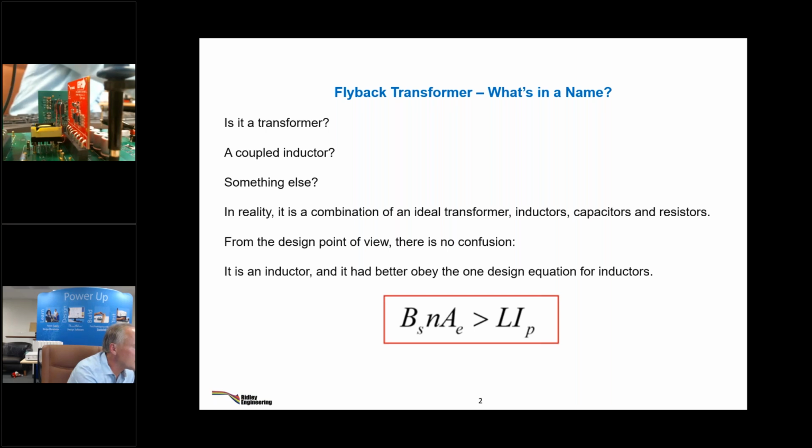Books often show NP equals V over 4.4. Stop reading books on magnetics, okay? They work in the wrong units. They don't work in Tesla. They work in Ørsteds and other things. And a factor of 4, no, I have no factor of 4 in there. He says, should NP be V over 4? I answered that question. So just stick to SI units. There's 2 equations, and that's all you need to know.